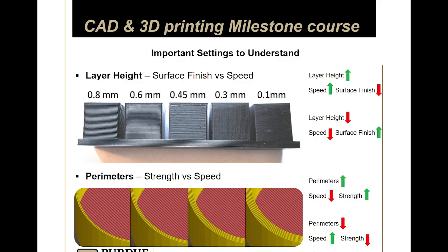But typically, I would say the number of perimeters set by the standard is usually around 3. Sometimes they do 2. For me, because I make more mechanical components that are subject to load, I usually increase it to 4. But sometimes I'll go 6 or even 8 depending on what I need it for. So yeah.